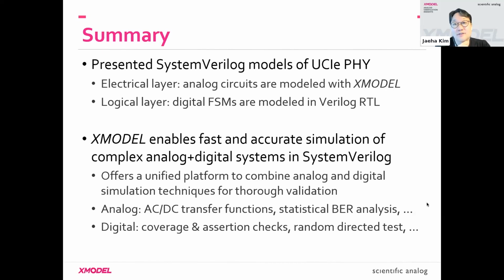The other non-linearity I can think of is some second order effects due to the finite rise and fall times. That one is not being currently modeled in our models right now because we're treating those outputs as pure digital, so this is 1 and 0. But if that's important, you can turn it into finite rise time, fall time signals, like we did in the DCC.